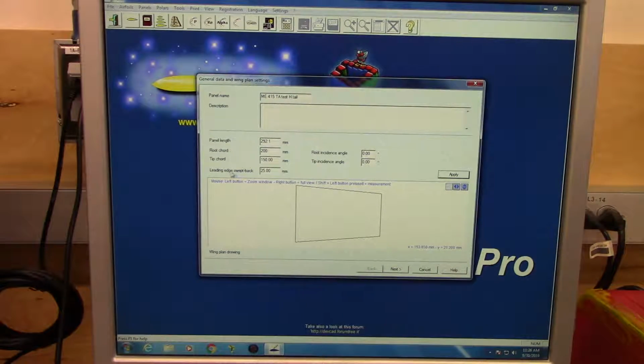And you see that I have my leading edge swept back a distance right here of 25 millimeters. I actually want to increase that to 50 millimeters, and hit apply again, so that my trailing edge is just flat. That's a personal preference of my pseudo design choice. You can have whatever taper ratios or sweeps that you want. Just make sure, again, to come prepared for those.